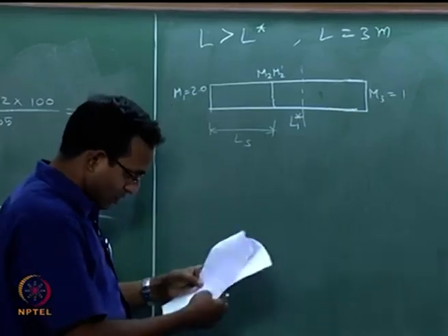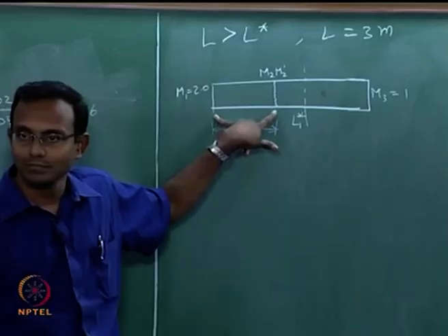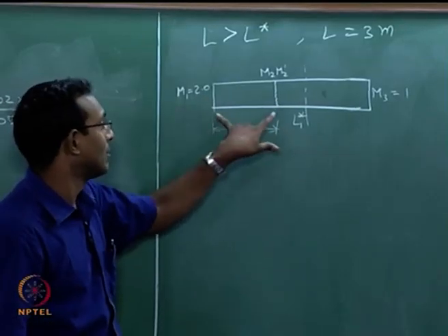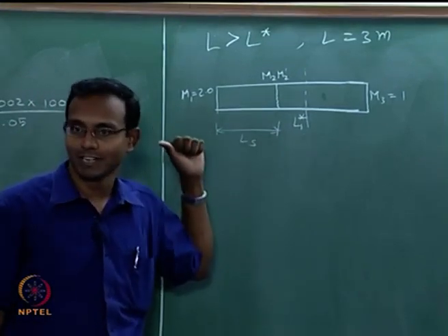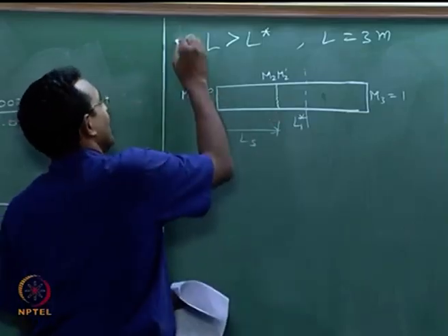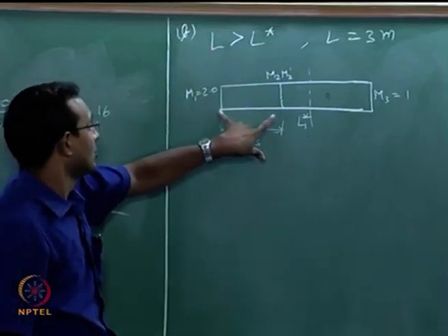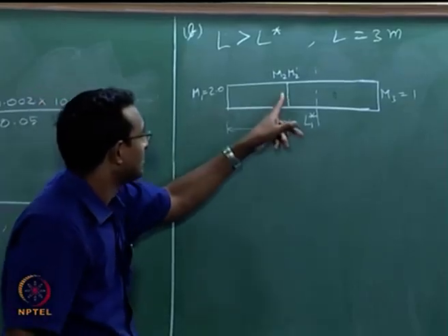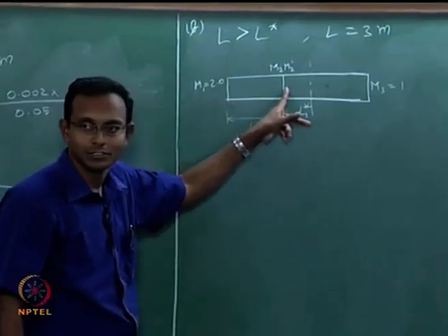So how will I solve this? I am going to first treat this part of the problem as supersonic flow going some length less than L star, which is just what we did in problem 2A. That was this problem, and this is 2B. I keep forgetting to label these problems. This is 2B, and so I will solve this as if it is 2A. After that, I have a normal shock problem. I will just go to normal shock tables and jump from here to here across this.